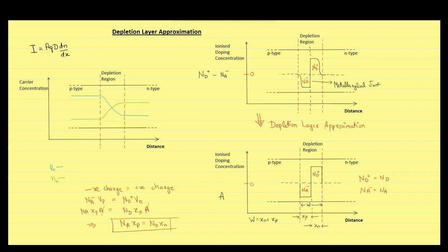If we consider depletion approximation, then you can see that the concentration gradient at the boundary of the depletion width would come infinite, which is obviously not possible. You could destroy all the power generating industries if you somehow created a semiconductor device delivering infinite current. This is not possible. That's why we do not use depletion approximation to calculate current passing through the depletion region.